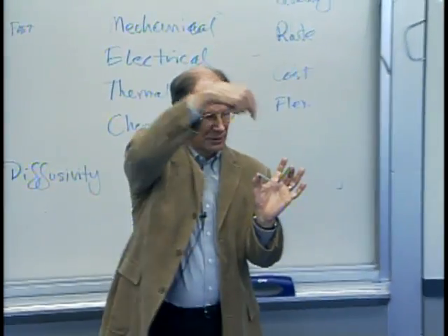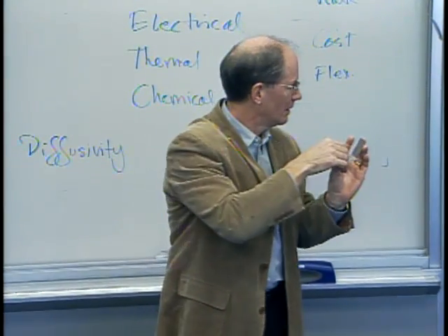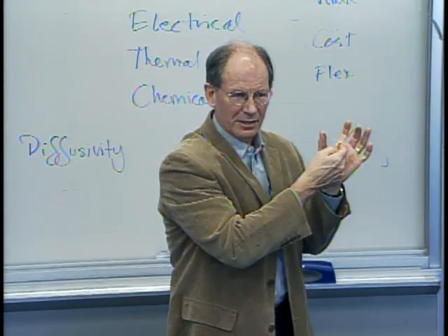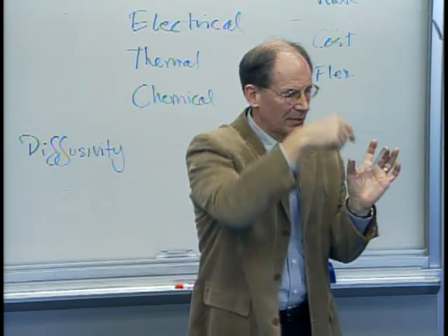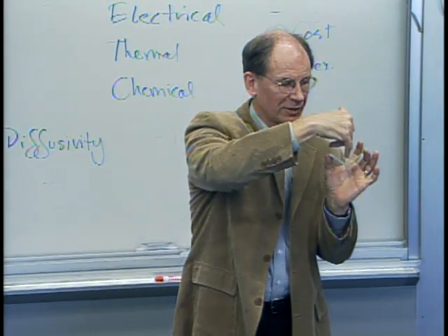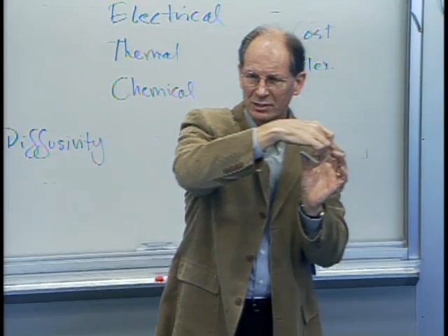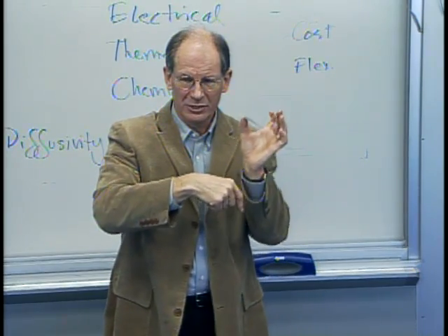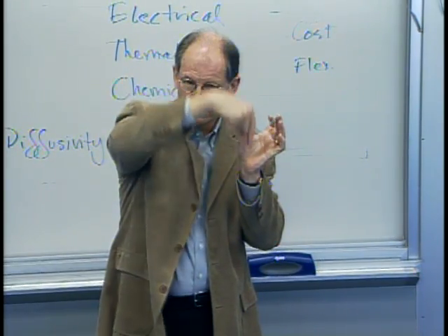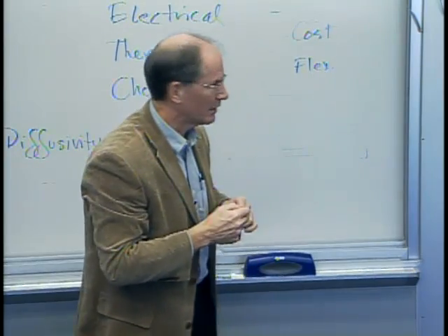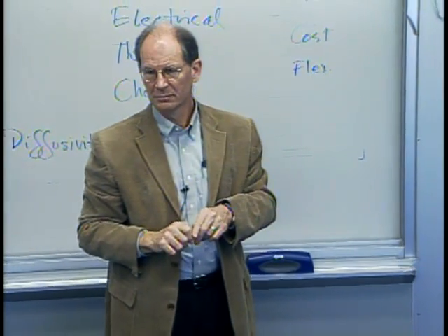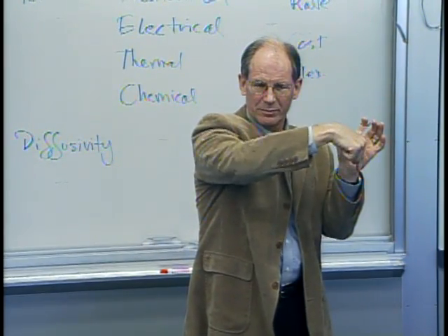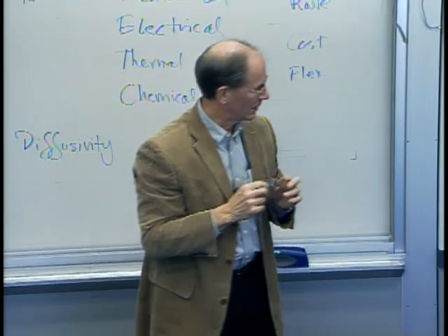Okay, I'm going to bend this, 3-point bending. I'm calling it serial because most of the action is happening right here. And I'm not using formed tools. You can even think of this as using knife edge tools, and I would get sort of this same shape. The main thing that determines this shape is how far I push down in the middle, right? Okay, so that's pretty flexible. If I want 45 degrees, I just take it down less. If I go down farther, I take it down more.